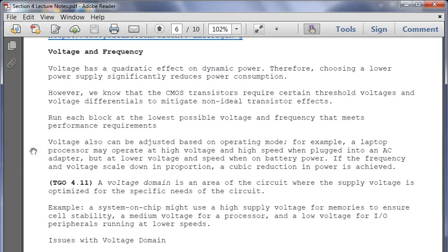So if you're able to actually reduce frequency and reduce supply voltage, you get VDD squared and the additional frequency reduction. So if that's something that your customers are willing to do, you can go for it. Go to power saving. Yep. And unfortunately, that's not so smart when you're giving a lecture and suddenly the screen goes blank.